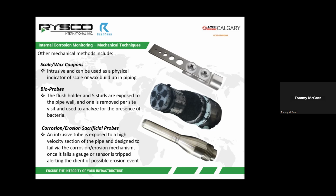Bioprobes, so that's a non-mechanical, meaning it's not electronic, probe. You have these studs that you can see in the image. You position that the same way you would a coupon. You can position it in the center of the line as well if you want to try and catch free flowing or planktonic bacteria, but in my experience the wall is a more representative method. You'll remove one of those studs per visit, and the biological buildup on that can then be analyzed, and there are many different techniques for that.